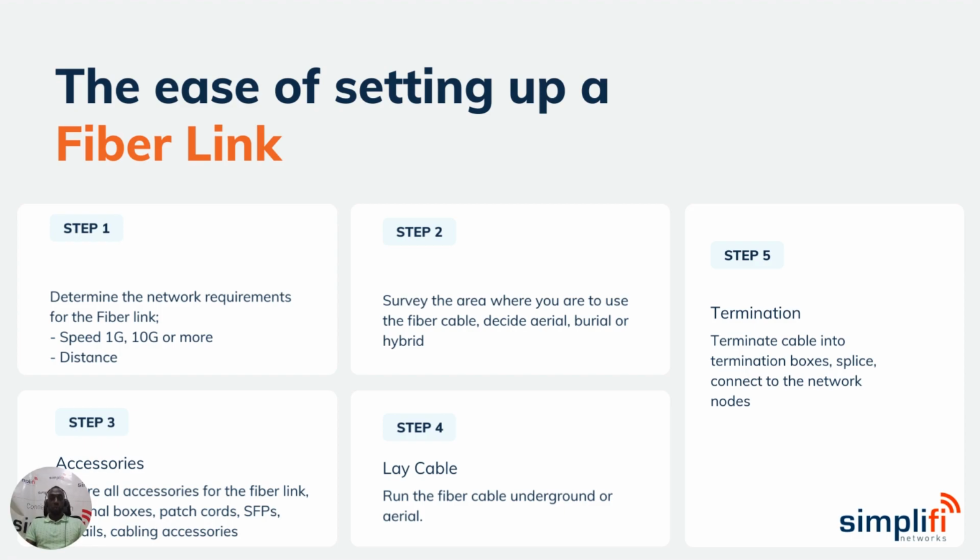Step 4 is you'd typically run your cable or lay your cable, depending on whether it is up or down in the ground. So you actually do the step of running the cable. And then lastly, you want to terminate and then test whether you have a link. And to test, you need some tools. Even to terminate, you need some tools. And that is what we're just going to look at in a few seconds.